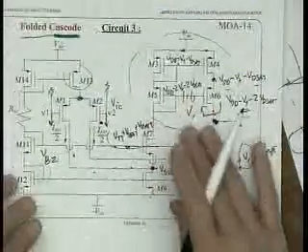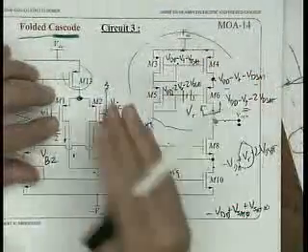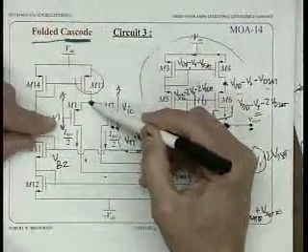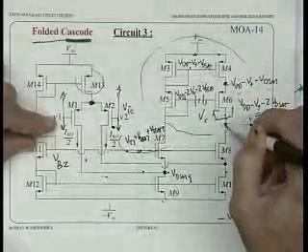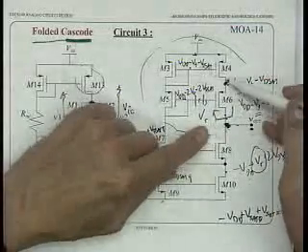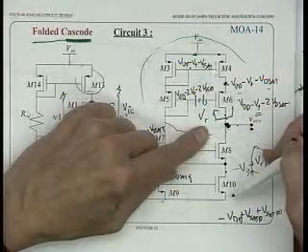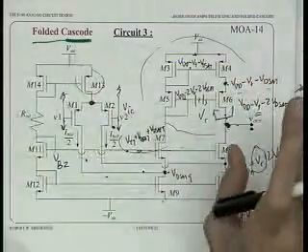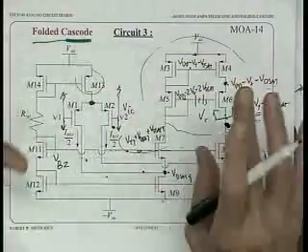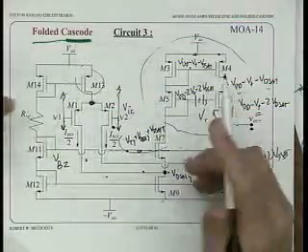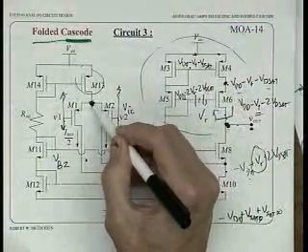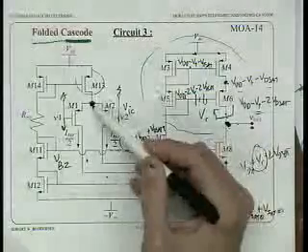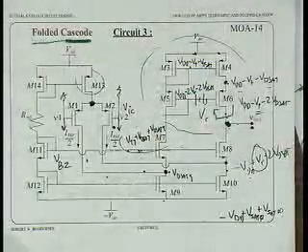This folding separates the output stage from the input stage, so we're no longer sensitive to this voltage here in terms of what the output swings to. The output swing is limited by M4 and M6 and M8 and M10. So that's kind of the magic of the folding. What you're concerned about is exactly why this is an interesting circuit. It got rid of the fact that this voltage right here, which was all tied up in our output swing in this case, is now not involved in our output swing at all.